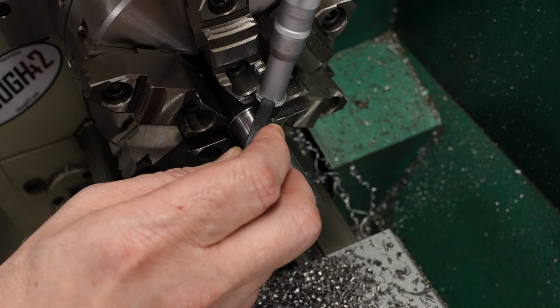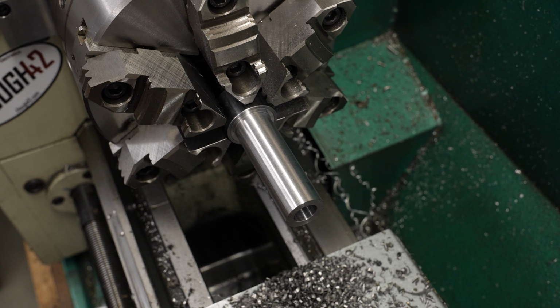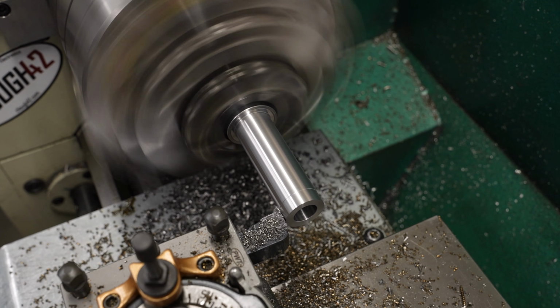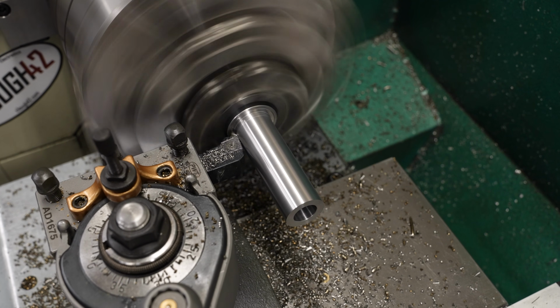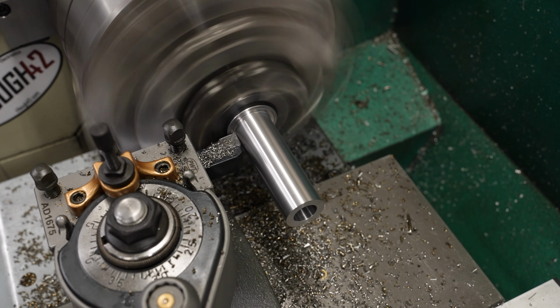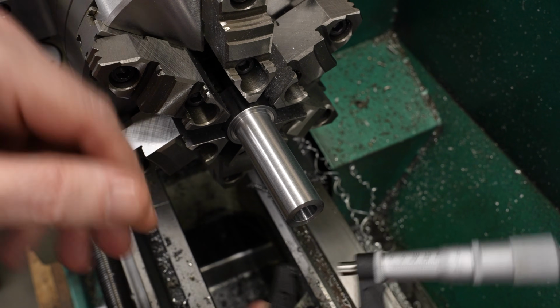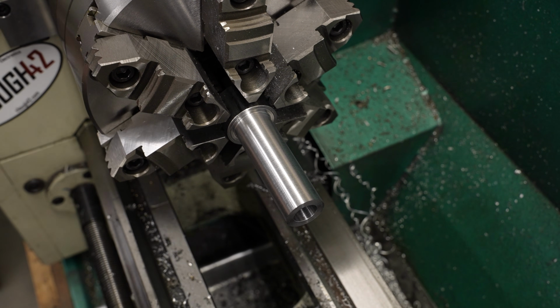So I'll take one fine pass, about 1/4 millimeter off the outside, take a measurement, put that in my DRO, and then go to the final dimension and take a pass to actually bring this to the target dimension. Now I'm targeting slightly under 20 millimeters, so it'll be a slip fit in the pulley. And that looks about right. Looks like we're about 20 microns under.